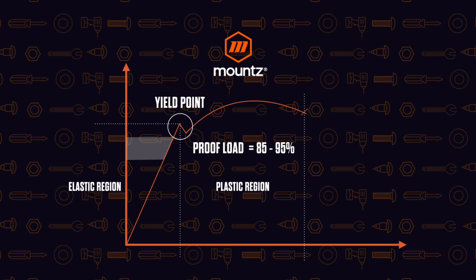Often you will see fasteners with specifications that give a proof load, of how many pounds or PSI it will take for that fastener to break. Typically we'll want our torque specifications for a given fastener to be within 75 or so percent of the proof load.